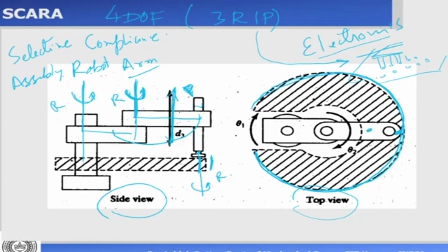And when I'm rotating this axis like this, it is coming till this point. Okay, so I'm getting another point here. Now, when the joint number 1 is rotating, what is happening? This point is being rotated like this to get a smaller circle. So this is one smaller circle, which is because of rotation of theta 1. The outer circle is because of L1 plus L2. So when it is in fully stretched condition, you'll get this circle. When this fellow is rotated and it is closed rather, then we'll be getting this inner circle. Okay, so what we are getting is the straight line here, which is being swept from the top view like this. We are getting two circles.